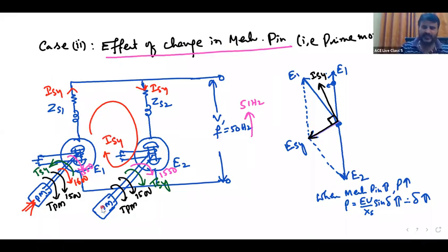When the second machine's frequency is decreased, its speed will reduce, and again the synchronizing current will increase, giving more braking action. When you are decreasing the speed, the synchronizing current will increase. The phasor difference is increasing. You are doing like this, and again it will be lagging.